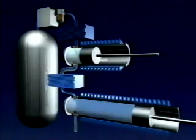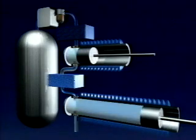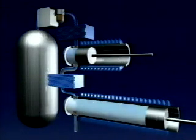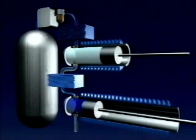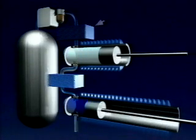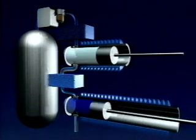After cooling in a positive displacement compressor, the air may go through more compression and cooling to reach a desired pressure. 5 or 6 stages of compression can build up pressures of several thousand pounds per square inch, while minimizing the use of power. Next, the air passes through an aftercooler. The air is cooled again, and moisture is removed. Without an aftercooler, condensed water from the ambient air would flood the compressed air piping system.